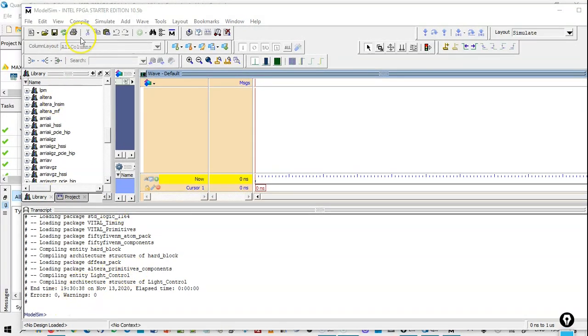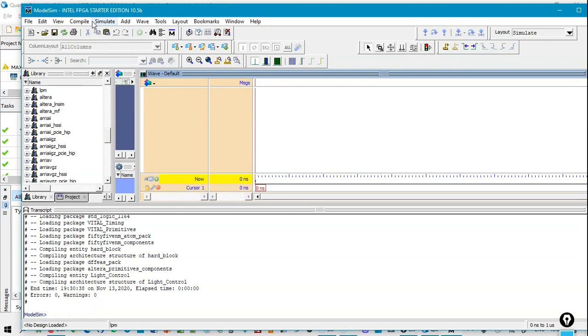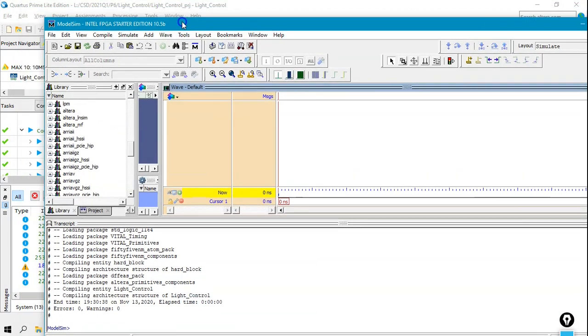Okay, so let's just start a gate level project to simulate what happens in real time in the circuit. But first of all, we have to go back to the Quartus Prime to see what happens and if the correct files are already there. Remember that now the simulation consists of the testbench file, the same as before, but then something else, like the architecture based on the translation of the technology view along with the delay, the file that contains the delays associated to the given technology. So let's see what happens for real now in the Quartus Prime.